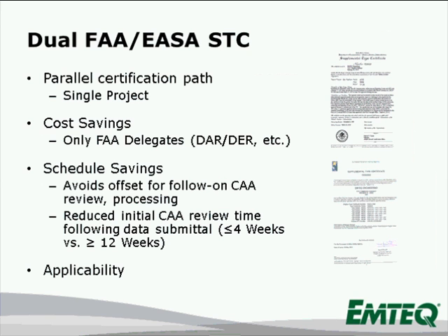EMTEQ also has the capability of obtaining an FAA and EASA STC in parallel. The benefit is that it's a single project that gets two of the more common regulatory requirements at the same time. And what this provides is a big savings in cost and schedule, primarily in schedule. The benefit with cost is that you're only sending FAA delegates, a DAR and a DER, in place of having to send FAA delegates and then perhaps later sending an EASA compliance verification engineer.